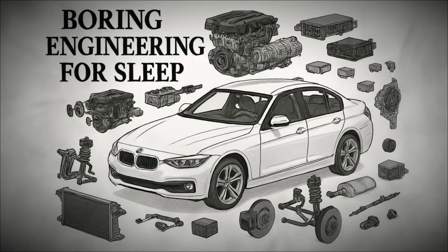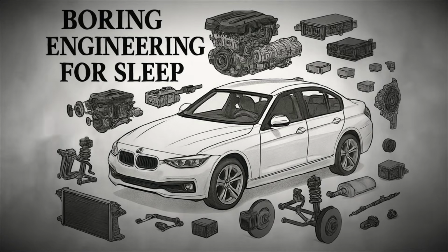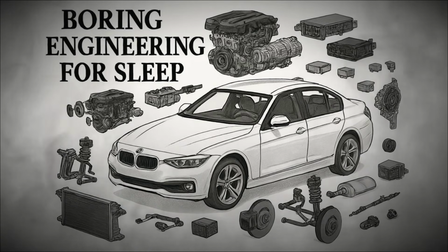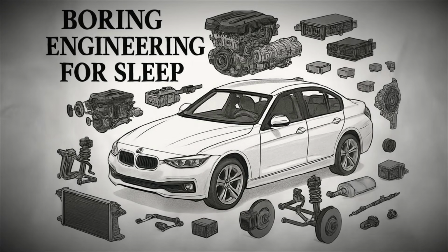The battery is the storage unit that holds electrical energy in chemical form, ready to be released when the ignition is switched on. Car batteries are typically lead-acid types, consisting of plates of lead and lead dioxide submerged in an electrolyte solution of sulfuric acid. Through chemical reactions, the battery can release electrons, producing a voltage of about 12 volts, which is the standard for most automotive systems. The battery provides the initial surge of electricity required to power the starter motor and ignite the engine, and it also powers systems when the engine is off, such as interior lights or the radio.